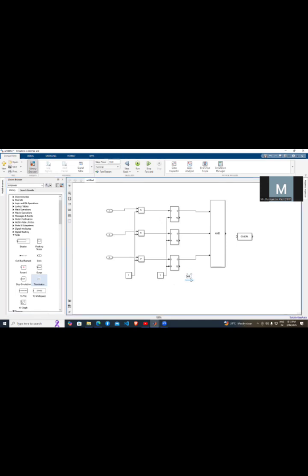You will require two more, so we press Control V, again Control V. Okay. So these are the terminators. The terminators we have connected. Similarly, we need to connect the AND function to the Double block, which converts the logical bit operation into double.